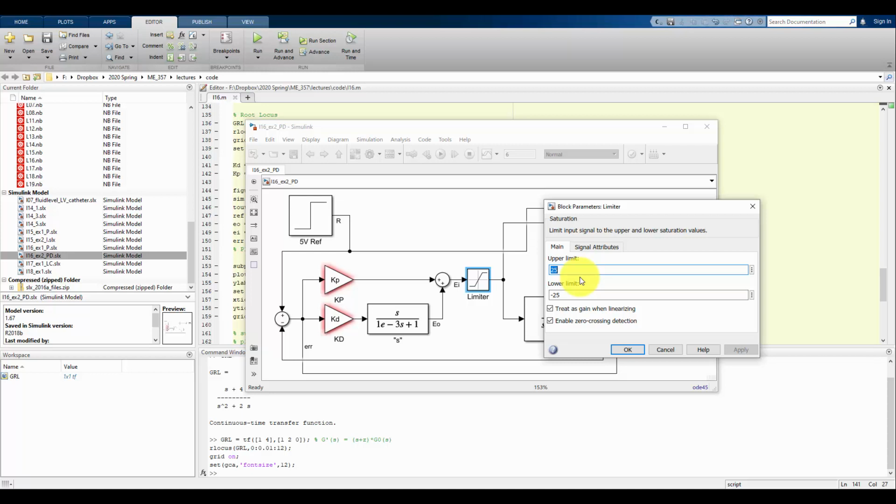So what I do here, I'm selecting right now just arbitrarily that the most EI could be is 25 or negative 25. So even if coming out of the controller, it's saying we need 1,000 volts or an infinite number of volts, it's going to say, you know what, the most we can apply is 25. And it's going to limit the practicality of our controller. I'm putting this in here just so we don't get some ridiculous infinite input demand into our system. Even though the controller wants it that way, we can't supply it.